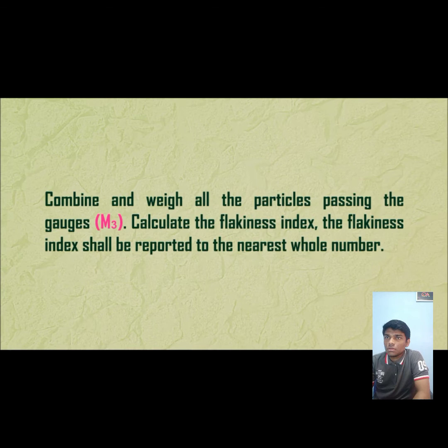Combine all the weight of the particles that passed the gauge. Calculate the flakiness index, and the flakiness index will be reported to the nearest whole number.